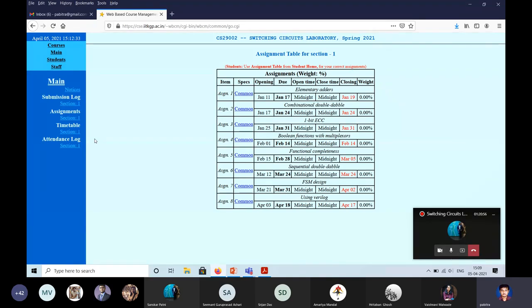If you give a test bench, you write something called a dump command. There is also, I forgot one thing, a display command to display the output, and a dump command to dump the thing. It will create a VCD file. Then you have another software called GTKWave. If you write GTKWave followed by this VCD file, it will plot the waveform.